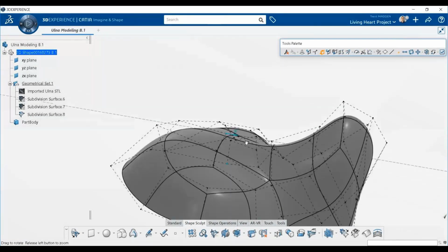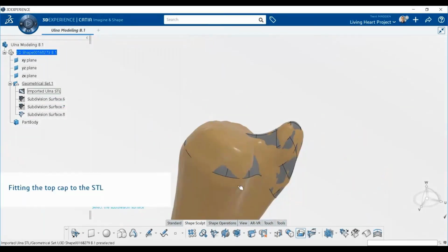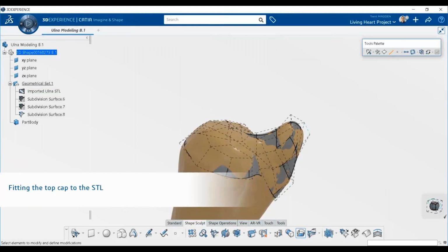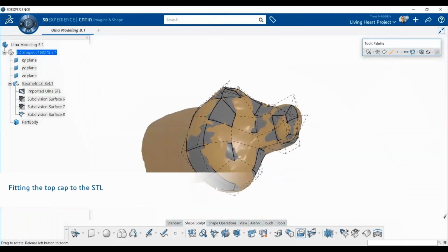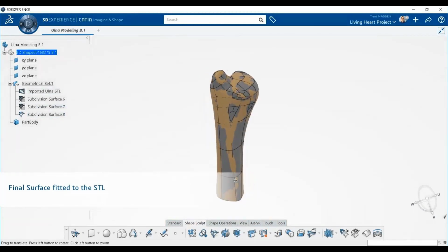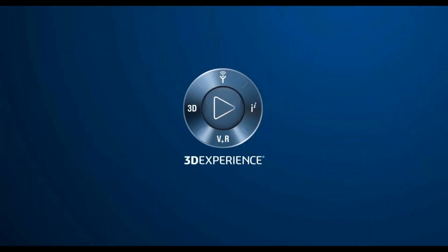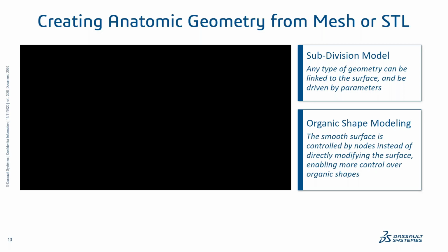Again, this is with bone, but this is the exact same techniques we would use whether you're creating papillary structures or a complex atrial surface. And from there, all we have to do is just extrapolate it down, simplify some of those patches, and then just do a fitting, and we have a very high quality ulna surface that we can then say is a template surface and is now ready to be used for further manipulations. And that surface is now at a high enough level of quality that we can mesh it very nicely.